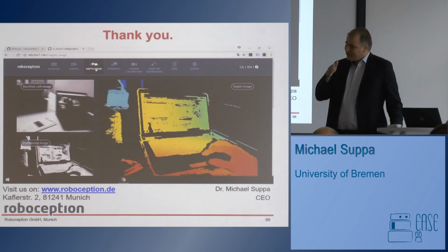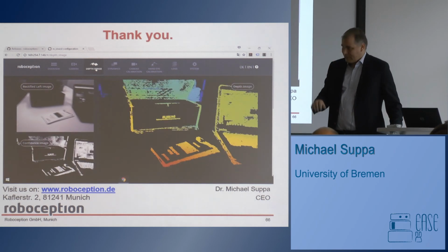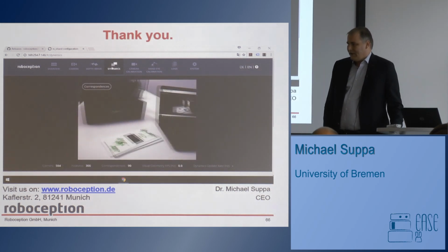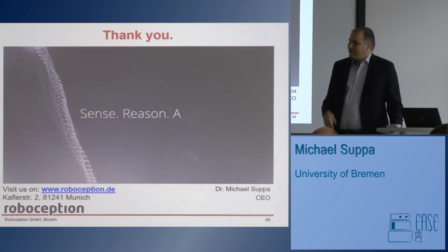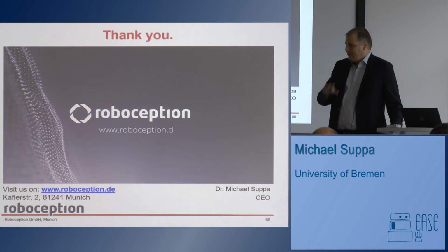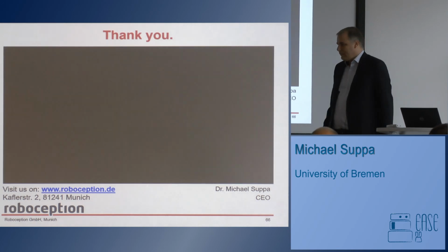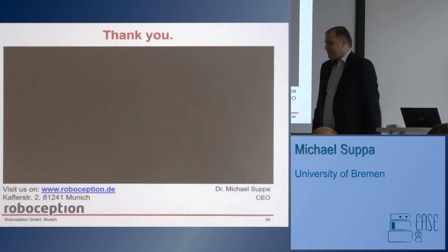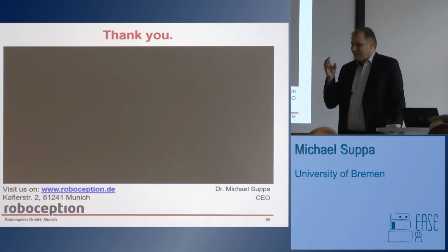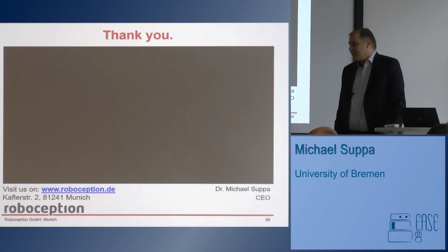There's also a procedure that tells how to show it to the camera, and this is how you get the calibration between camera and robot when it's mounted externally. When it's mounted on the robot, you basically just place one of these calibration grids somewhere in the workspace of the robot and look at it from different positions. That, of course, has a constraint that either the camera is fixed or the robot is fixed. So if you have both changing, that doesn't work in that case.